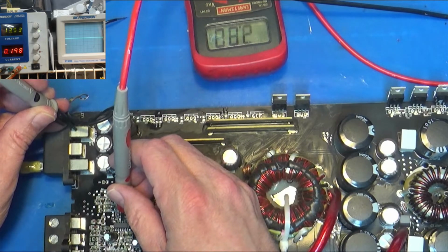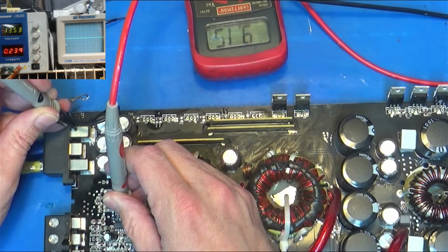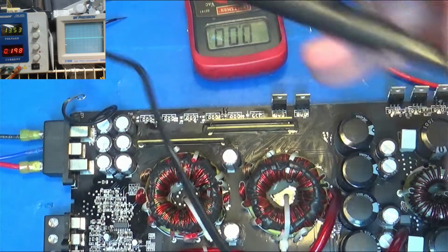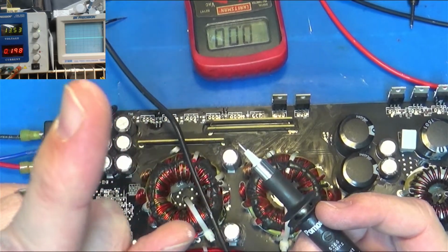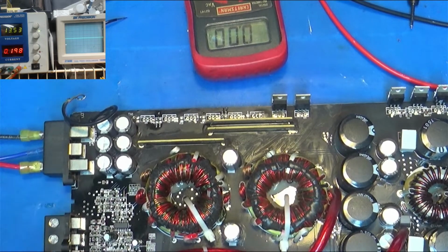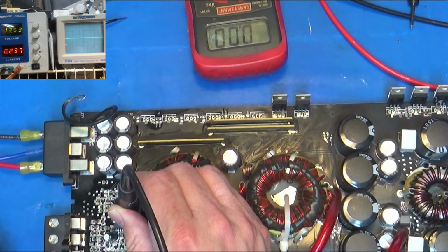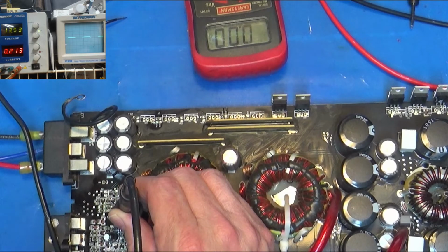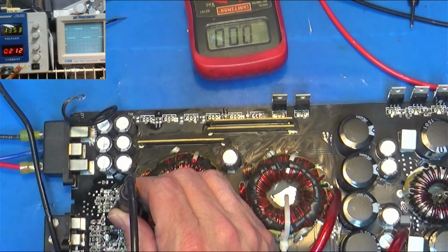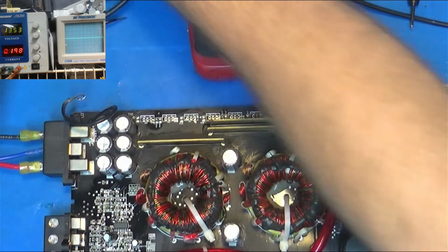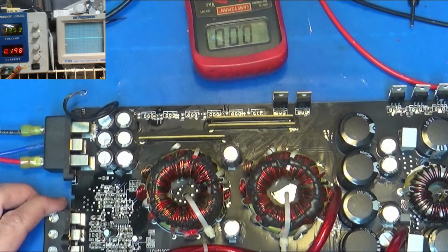So we're going to go back to pin 12. See the voltage there. It comes up. That's beauty. So let's go to the scope. Scope's going to be right here. Let's see if we can see anything on these pads now. Oh, no, sorry. It's just going to be the outputs of the pins because we have all the transistors out. And there we go. We have a square wave on pin 9, a square wave on pin 10. Shazam! The drive is working.